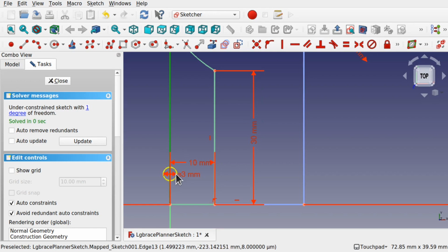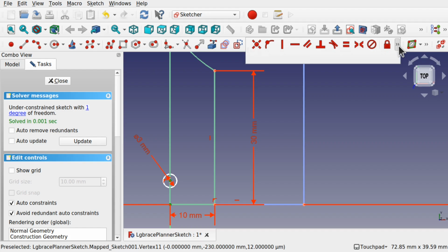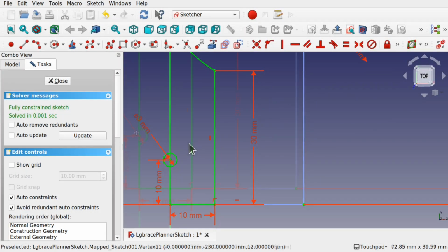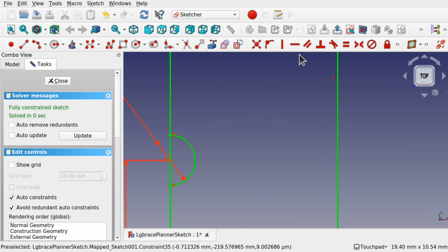We've got this line that goes through, and we've got a lot of constraints that are hiding that. Make sure that's 1 centimeter away. 10mm, and we need to come in and do the same in here, so let's trim in there.